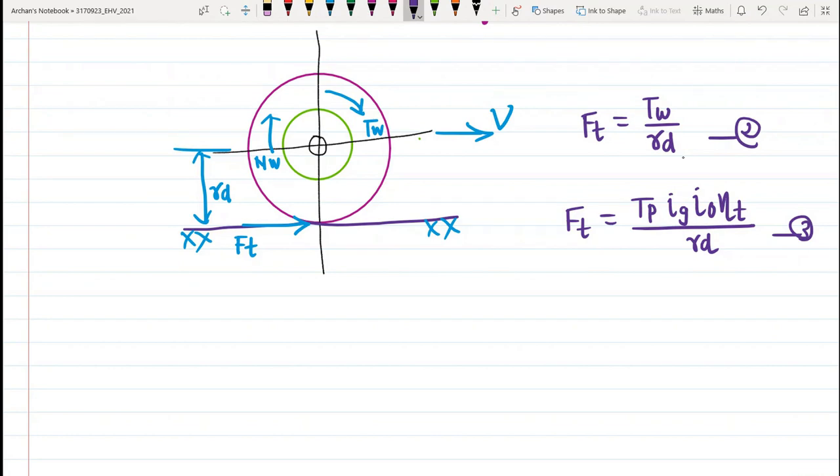So the total mechanical efficiency of the transmission between the engine output shaft and the drive wheels or sprocket is the product of the efficiencies of all the components in the driveline, right? As a first approximation, the average overall mechanical efficiency of a manual gear shift transmission is 90% for direct gear, and 85% for automatic or other gears. A transmission with a very high reduction ratio will be around 75 to 80%.